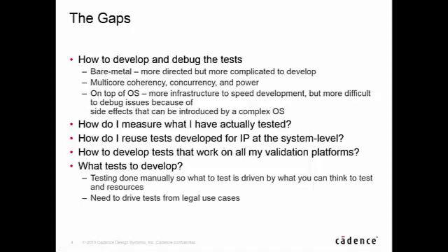This is a common problem of bringing in IP, adding it to the system, and wanting to apply system-level tests to make sure that IP stays functioning. The most common of these is power management. Your SoC has a power management protocol, and you bring in a new piece of IP, and that IP has to operate across the different power domains and transitions. As a consequence, you want to test that IP, not to retest all the work that you've done at the IP level, but to really validate that the IP stayed operational across these system-level